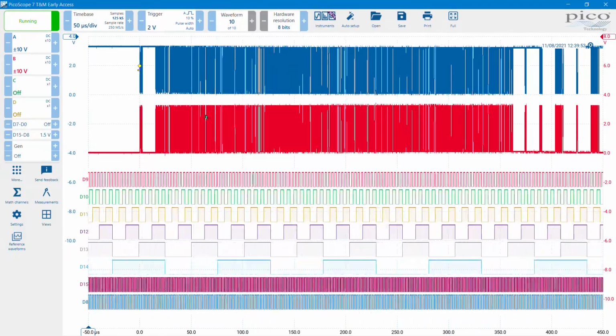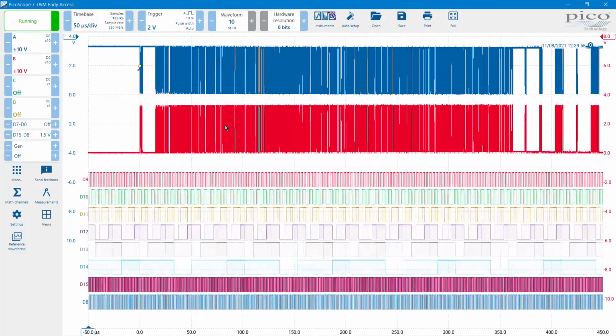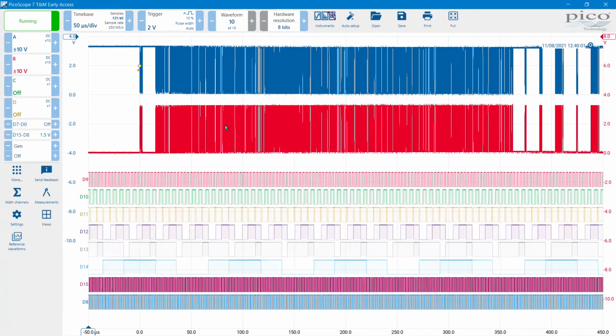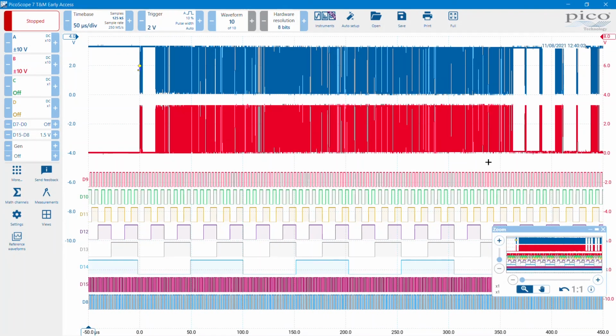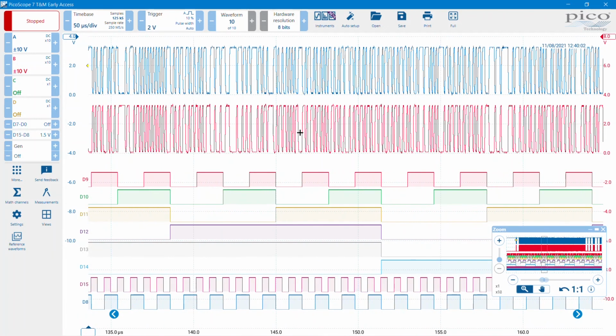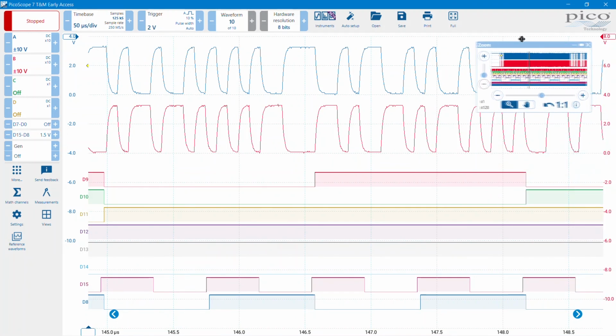The main area that you see here on the screen is the waveform display area, or the graph area, and let's just freeze that for a moment, and you can zoom in. So zoom in on a captured waveform, and then on the graph display you can organize that display pretty much in any way that you like, with a combination of analog channels, digital channels, reference memory channels, math channels. They can all go onto that graphical display.